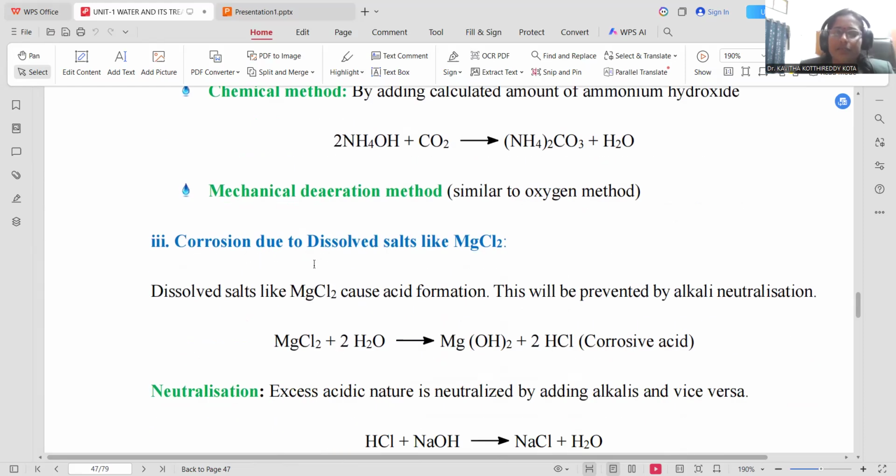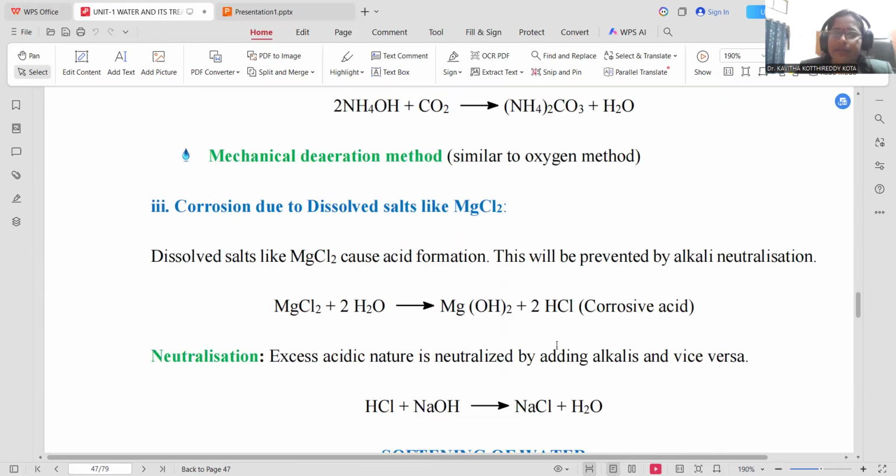Another possible cause of corrosion is the presence of magnesium chloride. This is also a cause of hardness. Whenever boiler feed water is contaminated by magnesium chloride, it also has the provision to generate acid within the boiler. Magnesium chloride, upon reacting with water at higher temperature, gives magnesium hydroxide and free hydrochloric acid, which is a mineral acid. Mineral acid is more prone to accelerating the rate of corrosion, being a catalyst for the corrosion process, so the boiler body decays and its durability is lowered.